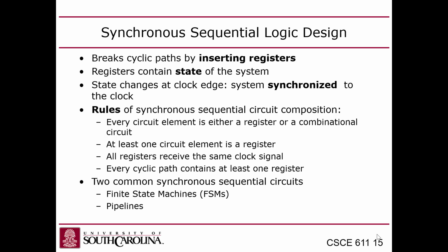So we're going to have this sequencing that has to happen, where once the user initiates something, it goes through a sequence of clock level operations. You guys with me? So that's something we can use a finite state machine for. A pipeline, on the other hand, is when you have registers and you move data through a sequence of registers, almost like a shift register.